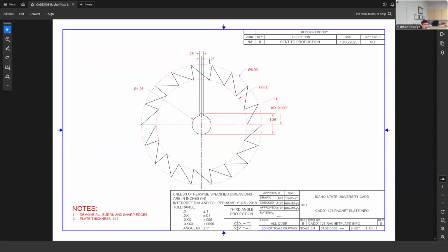I need an eighth of an inch measurement to locate it. Yeah, that's a location. And that's where somebody might debate you. Your checker could grab that and say, I don't think you need that eighth of an inch because it's clearly shown that it's centered with the center. And I'm like, yeah, that's fine. You could choose to drop that or not. I'm going to leave it because I do like it as a location.